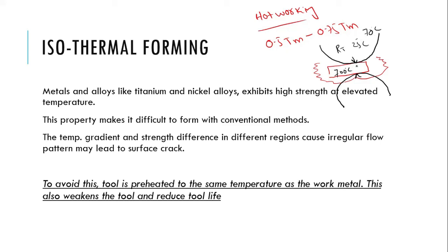The second one, because of the sharp rate of heat transfer, the atoms here rapidly crystallize. There's a rapid crystallization here, and a fine grained structure starts to form. So the plastic deformation within the same material differs. The plastic deformation pattern in different regions of the material is disturbed. So that is why it is not desirable.